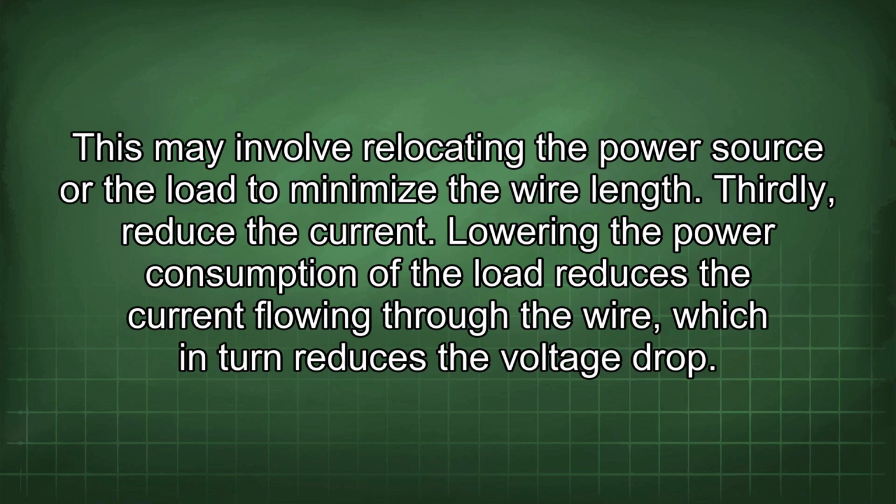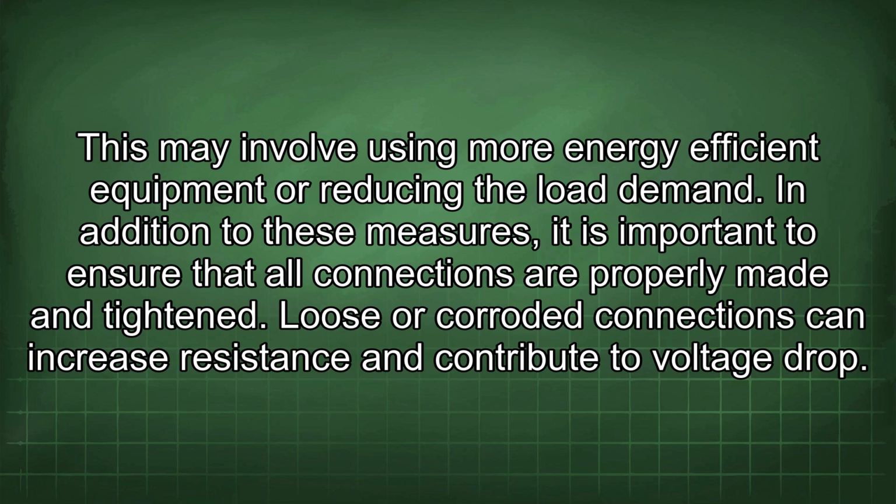Thirdly, reduce the current. Lowering the power consumption of the load reduces the current flowing through the wire, which in turn reduces the voltage drop. This may involve using more energy-efficient equipment or reducing the load demand.